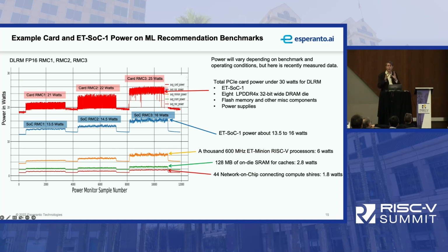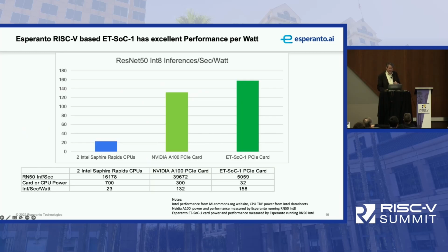So if we found that we were being performance bound by the NOC to NOC interface, we could raise the frequency of that interface. That would raise the power up. And so you've got a multi-variable optimization problem here. For the particular problem you're working on, how do you want to optimize it? So there's a lot of knobs to turn in terms of getting the best performance out of your particular system here. Okay? So how does it perform compared to other things out there?